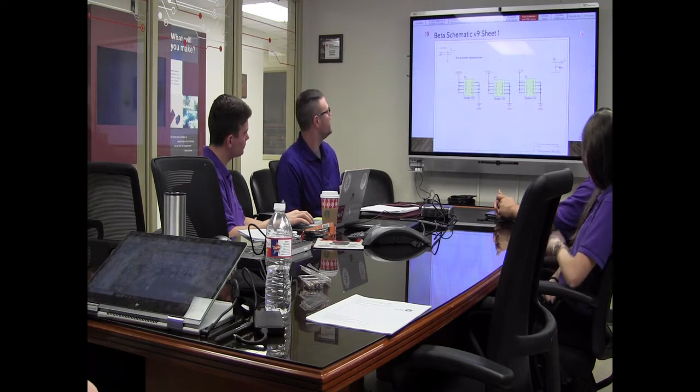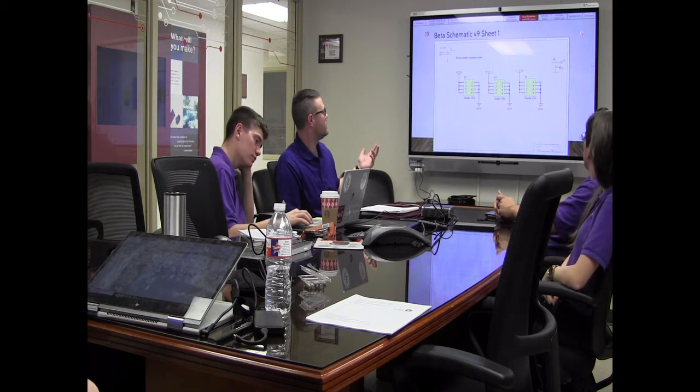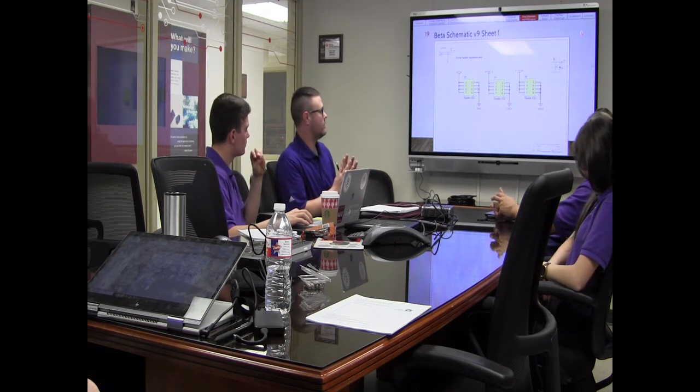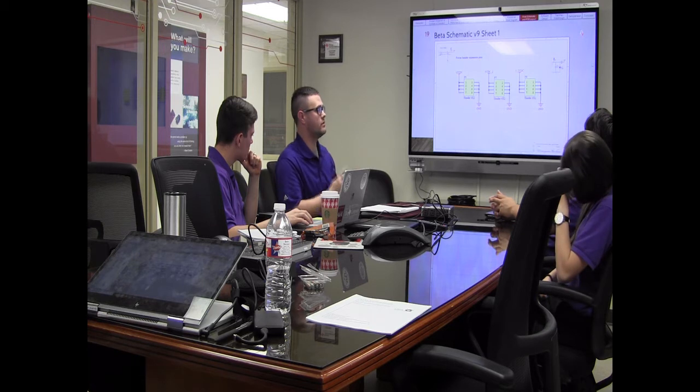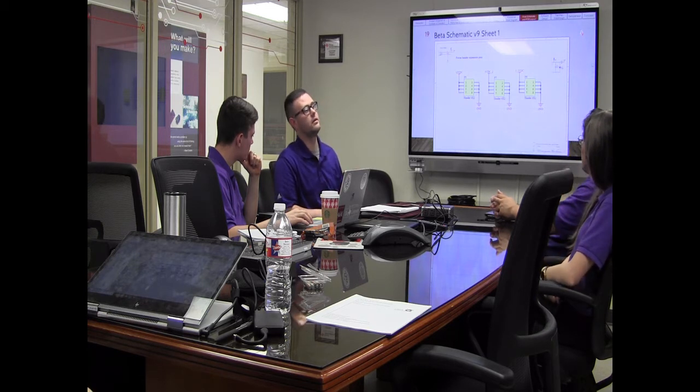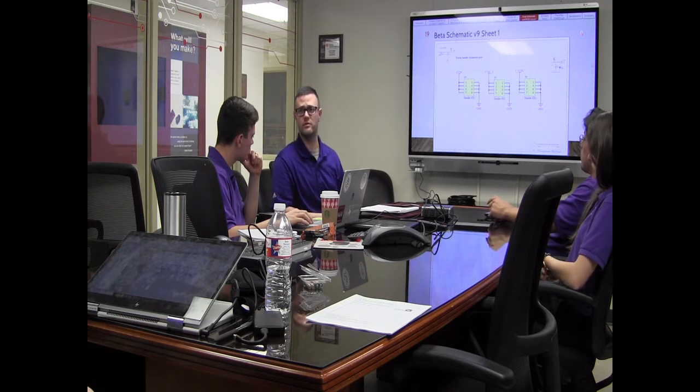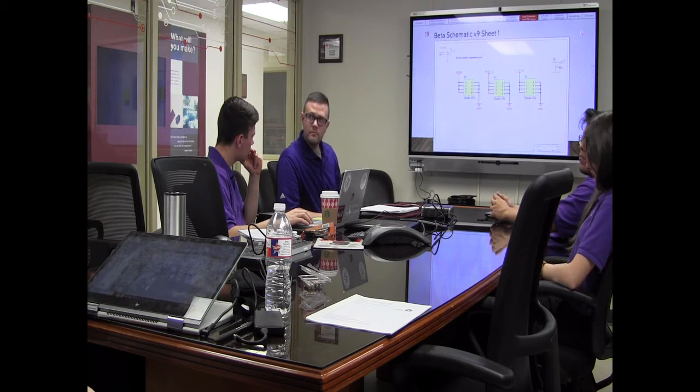Exactly the same design. And then we also have power header expansion pins where it's an 8-pin connector, and one side of it's all either 12 volts or ground, next one's 5 volts or ground, next one's 3.3 volts or ground. So if you want to power something else, which in one of our cases we're powering an Arduino in order to talk to our AC unit. But those are the same voltages then that are running to your 40-pin connector. Yes, exactly. So it's extra expansion pins, so you have that if you need it.